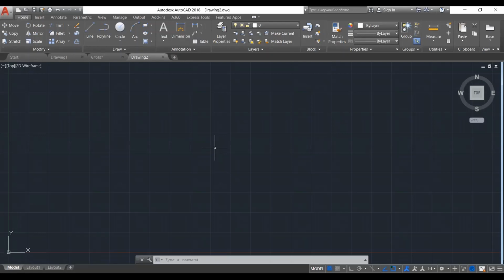We will know first these two orders, and then we will know our secondary orders, which will support me and give me a great shortcut for drawing my patterns. So the first order, how to draw a line. When I need to draw a line using the CAD, I will give the CAD this order. I need to draw a line, so it's a line. Its shortcut is L, enter, or I can see above here in this bar, here how to draw a line.